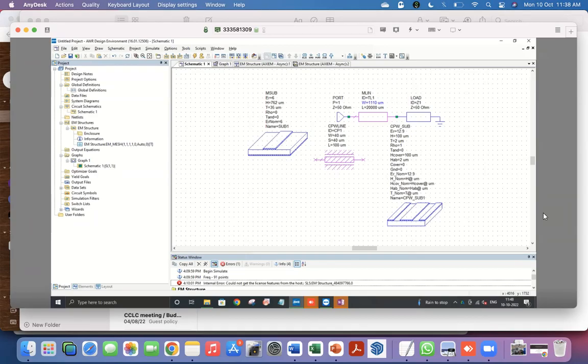So the only parameters you define are the effective electrical length and the characteristic impedance. The characteristic impedance is important, of course, because that tells you the ratio of voltage to current at any point for one direction of wave propagation. So the physical models are useful to get a more realistic sense of losses and maybe other mismatches you might have. But again, these also have limited accuracy.